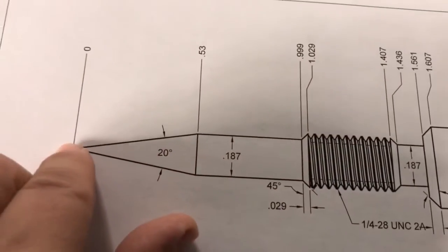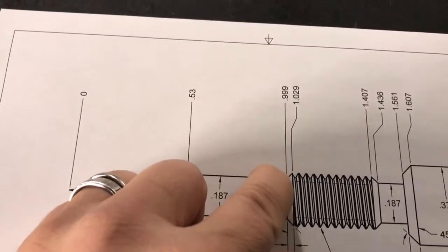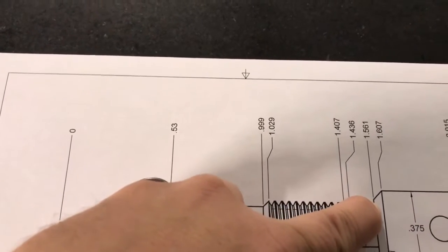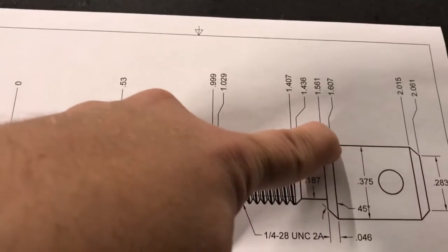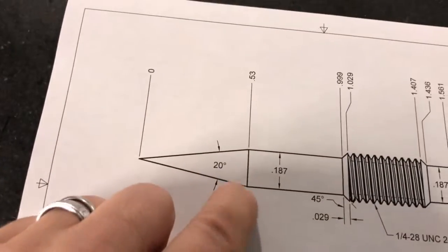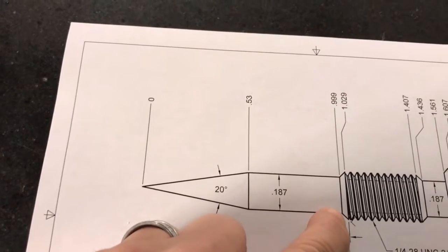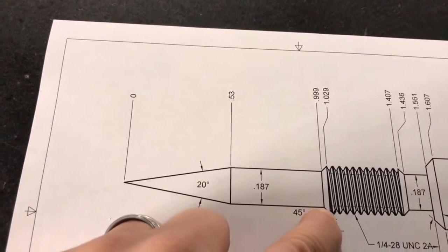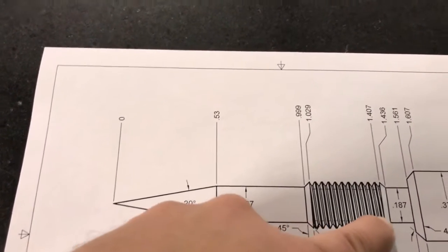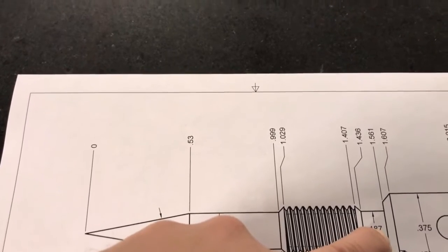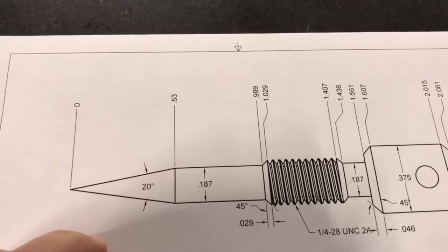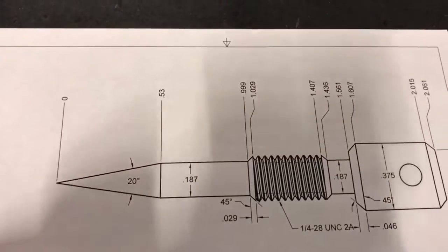One, I can go from this point to here, up to the top of the chamfer, over to this point, down to the chamfer, and so on. Or I can go from here to here. Then there's a button that allows me to do a chamfer, or a square corner back up to this point, then a chamfer there, straight over, a chamfer again, and feed up to here for a chamfer there. Both work, and they'll both create the same profile. It's just two different ways to do it.